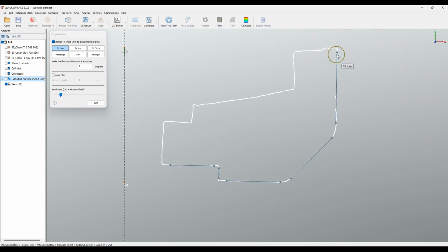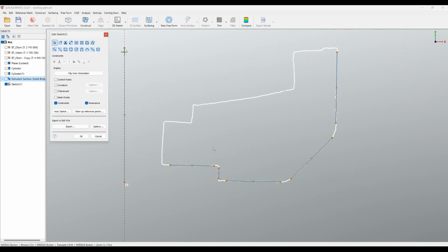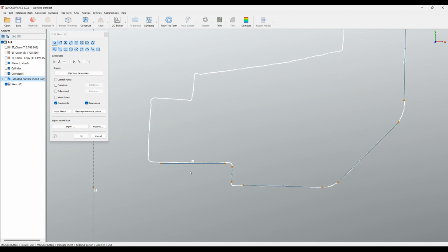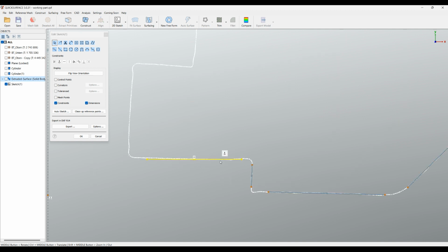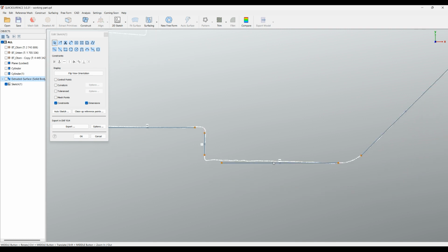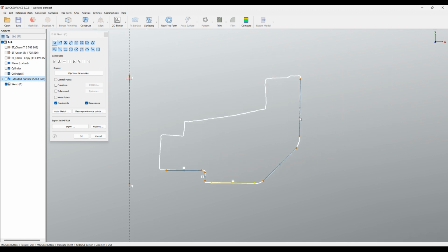As you can see, it created the lines. I can just press back, but it's in your hands to actually make the design correct. For example, you can make this horizontal, you can create these verticals, and you can define this in the best possible way for you. I can just create this as a vertical line. We noticed that our diameter was 37.5, which technically means that we need to create this with the correct radius.